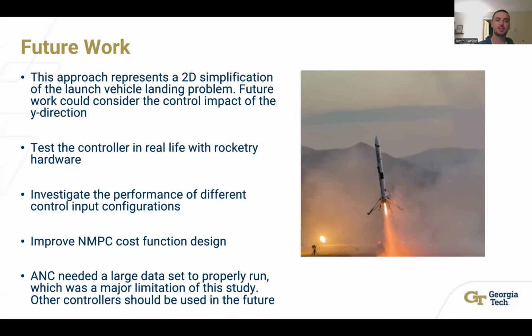We could also test the controller in real life with rocketry hardware. In addition, on top of looking at different control algorithms, we could look at different control input setups. Of course, we were limited to our gimbal angle, our reaction control thrusters, and our main engine thrust. Depending on where those are configured and how they're configured, that could have a large impact on the overall performance of our system, regardless of what control algorithms are used.